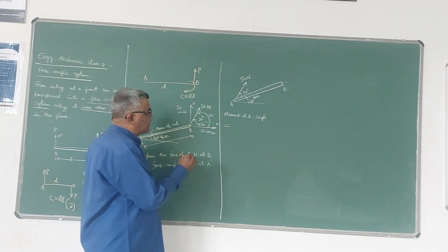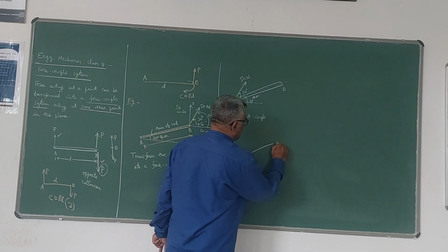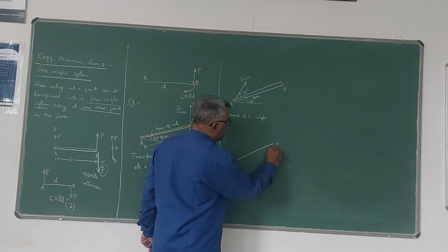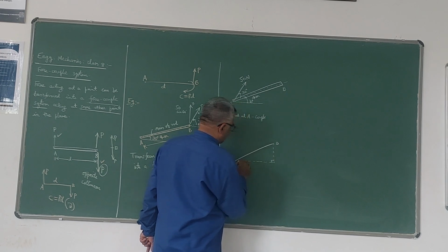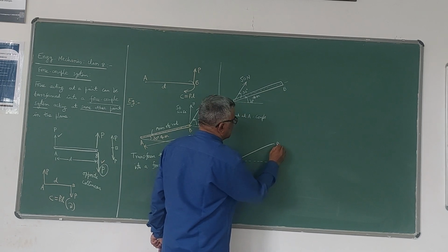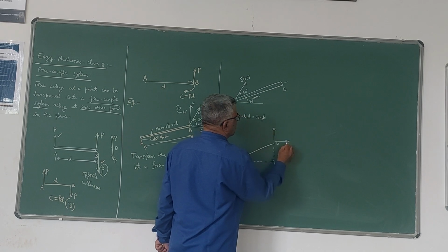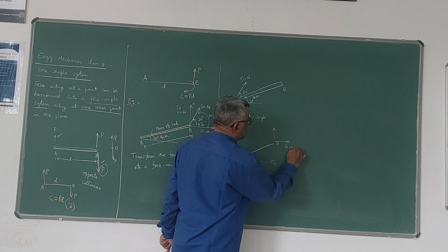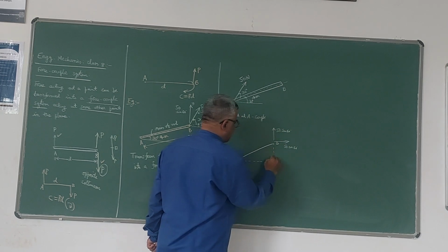Now let us calculate that in this diagram. So here, if you take this as AB, if you draw the perpendicular here, and if you take this as C, so at B you have horizontal as well as vertical force. Horizontal is 50 cos 60, vertical is 50 sin 60. Now I use these two distances.